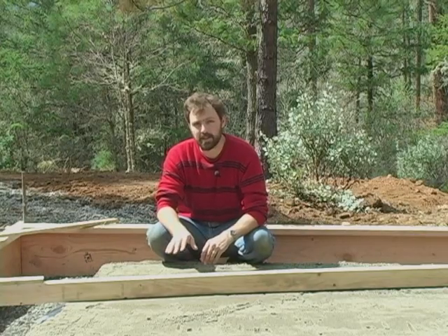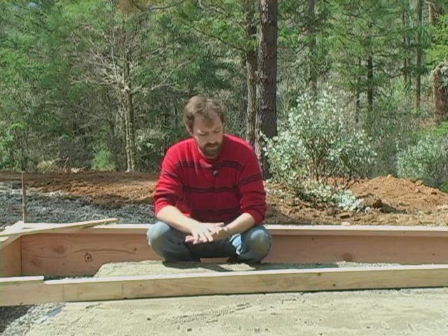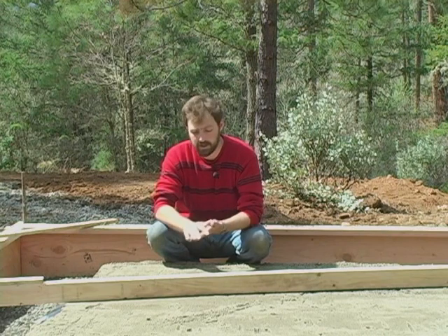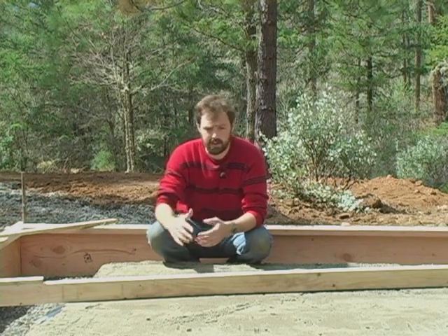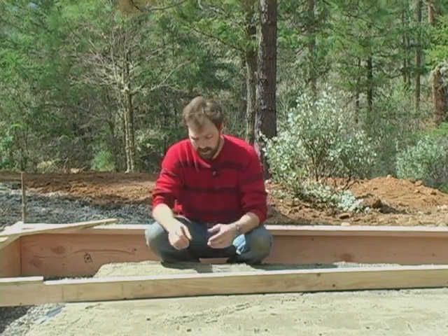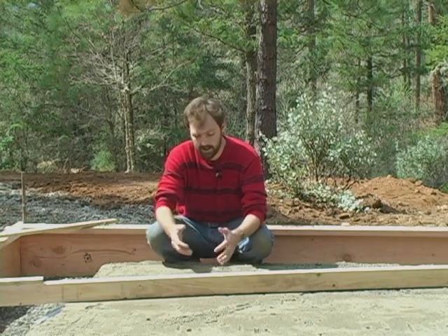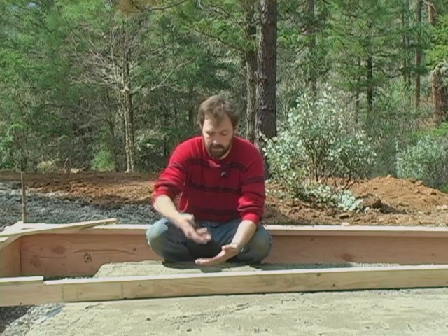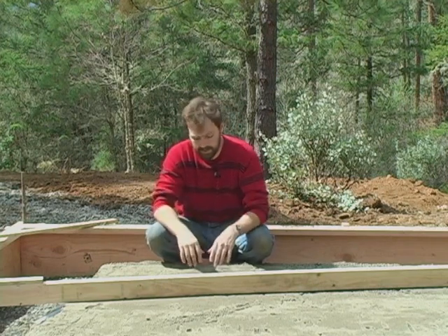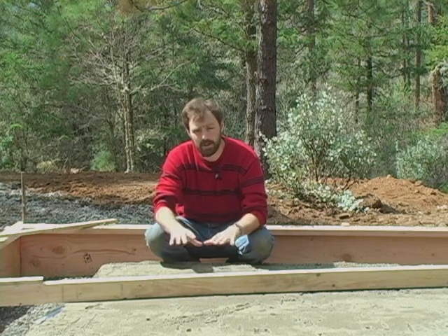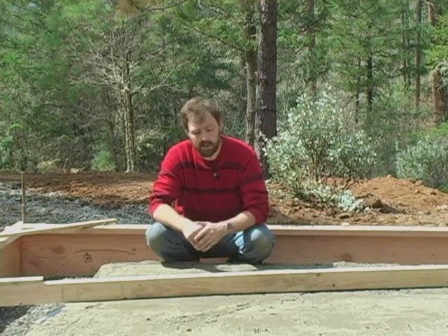I've got sand on top of the insulation, and the major reason for this is it allows the concrete to cure at equal rates in both directions. Above the concrete, there's not a whole lot stopping that moisture from coming out. If we have something water resistant right underneath the slab, it'll want to hold that moisture and it'll wick all the way through the concrete and dry unevenly. So this way the moisture can sink down into the sand and stay as a wet base and keep a slow cure for the concrete.